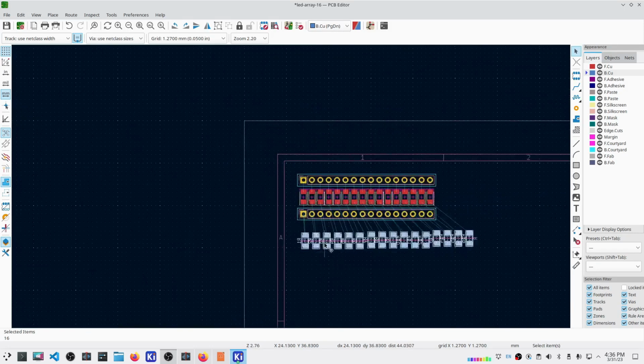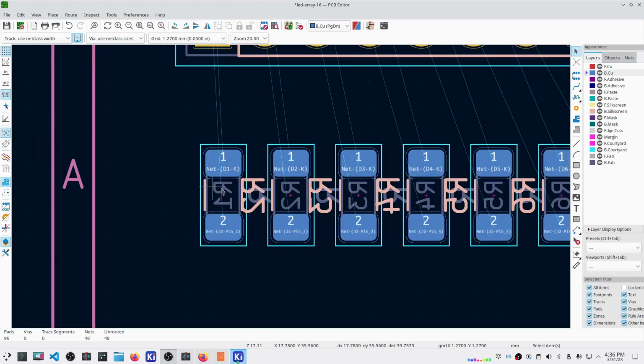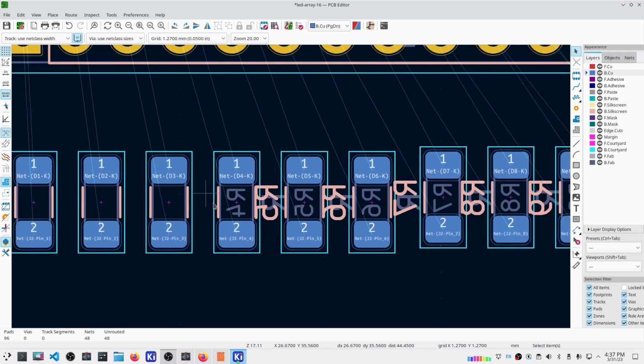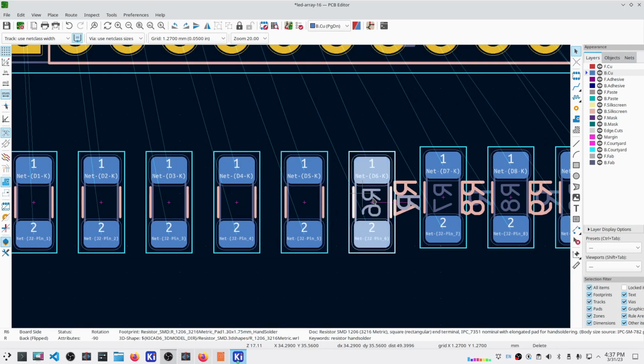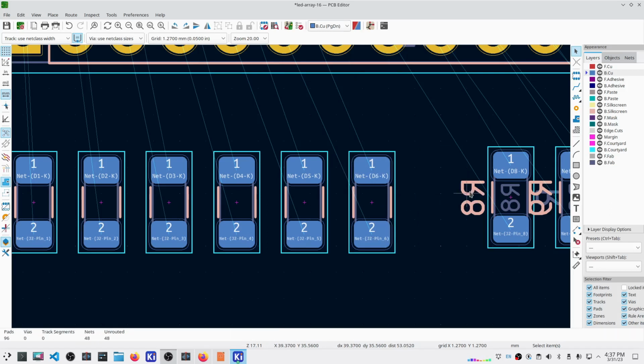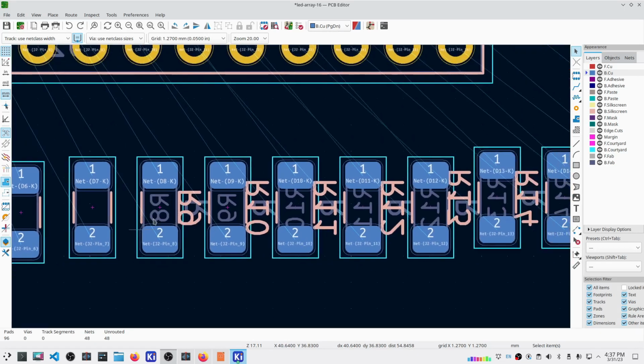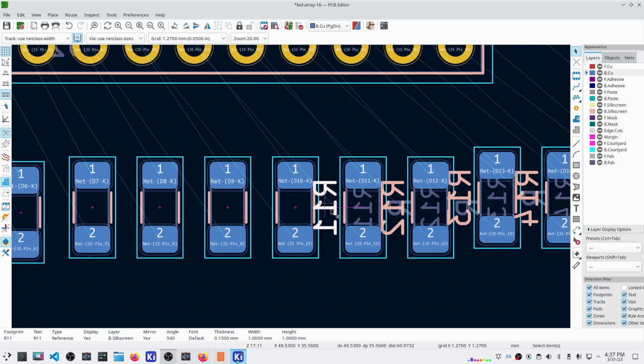And so I'm going to stick them here for the moment because I ultimately end up needing to do the same thing. Now, keep in mind the values of these resistors are really not going to matter as far as the PCB is concerned. But in reality, I'm probably going to use all 1K resistors. And that's only because I've found that the 220 ohm resistors leave the LEDs just a little bit too bright for the camera.